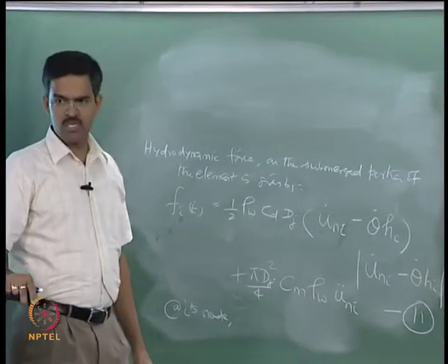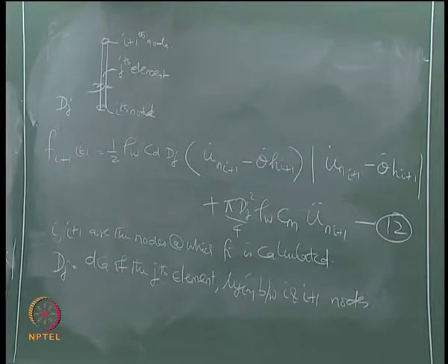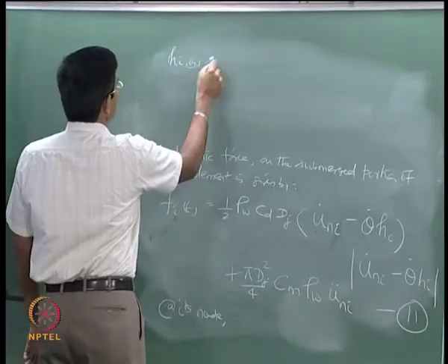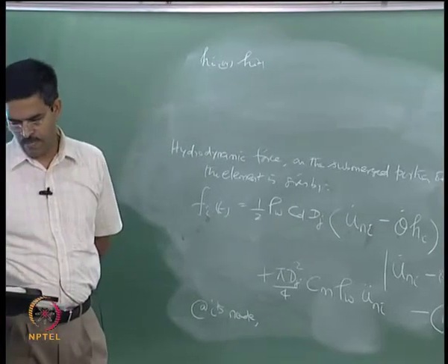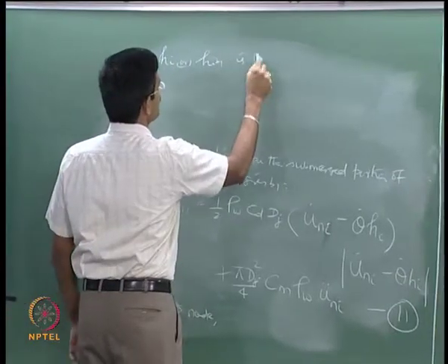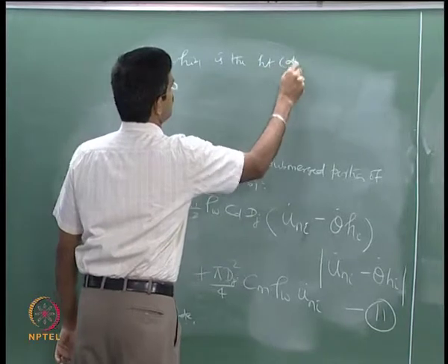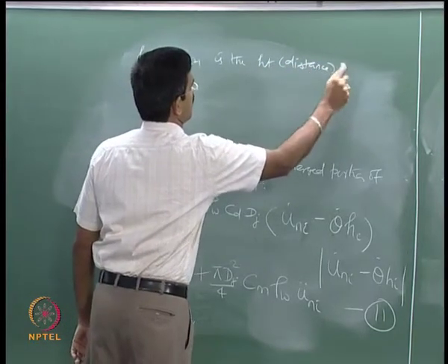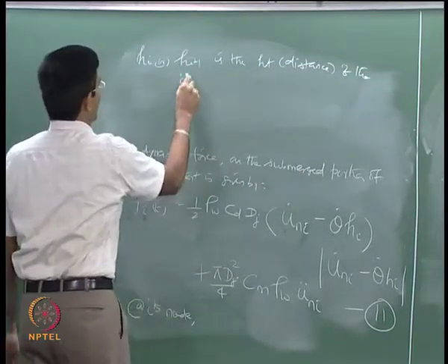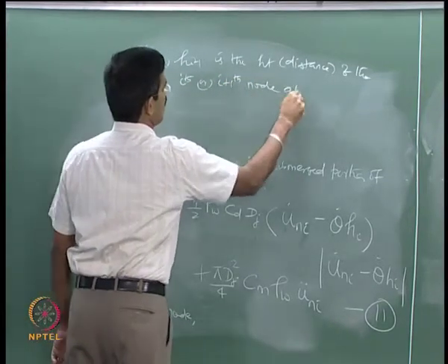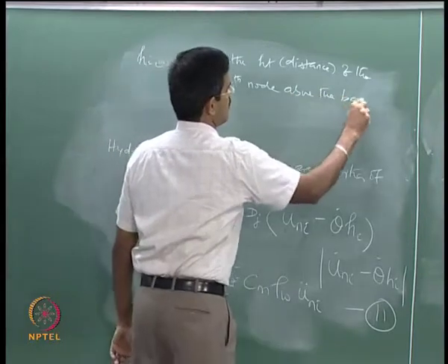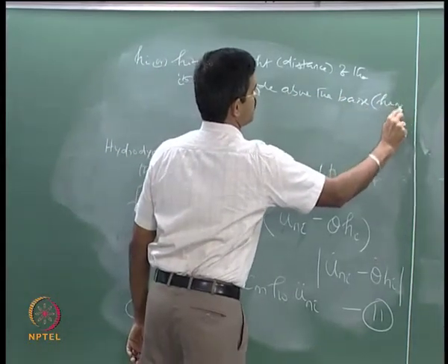Theta dot is the angular velocity at the ith and (i+1)th node of the tower, which is my displacement degree of freedom. h_i or h_(i+1) is the height, I should say distance, of the ith or (i+1)th node above the base. Which is the base? The hinge.